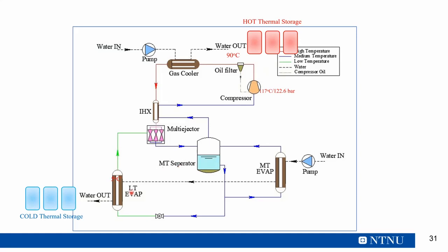And with the support of that, we are going to have cold water to handle the air conditioning side of the unit. And the major important part of this is we are going to implement thermal storages on both sides, hot thermal storage tanks and cold water thermal storage tanks. The purpose of this is to handle the peak load hours.